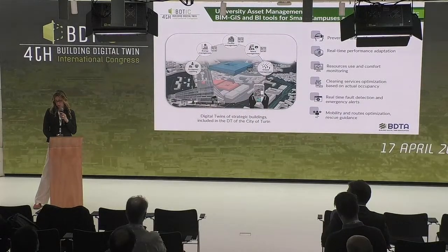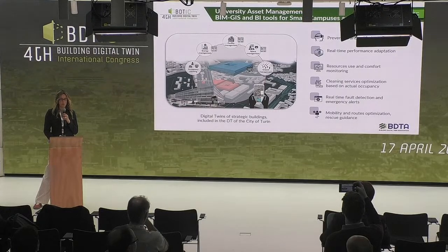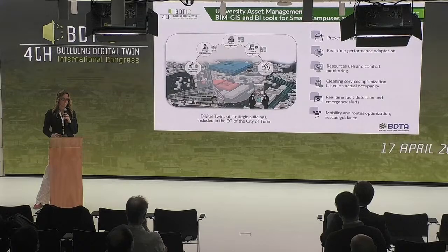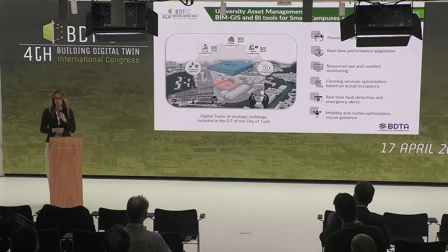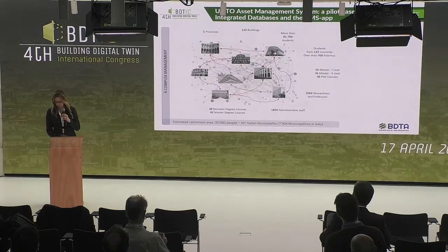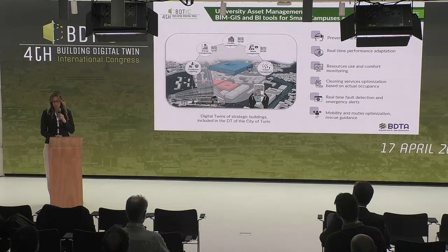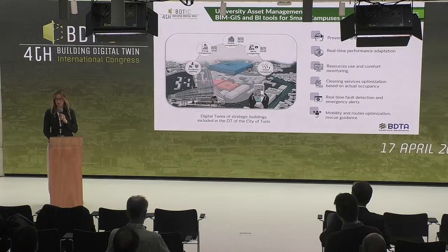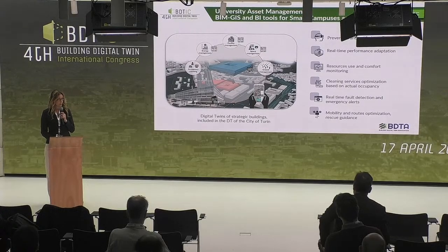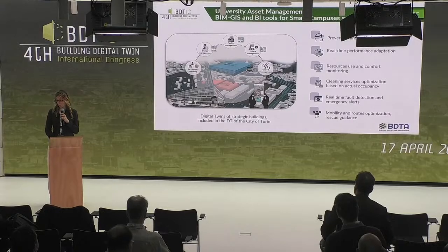So we created this digital twin. In this moment, we have some pilot buildings where we are collecting data from the classrooms about the indoor conditions, for example, temperature, humidity, CO2 concentration, VOC, and so on. And we are extending the information about the people flow, the real occupancy, because we know that if we want to optimize, for example, also the HVAC system functioning, we need to know the correct number of people inside the spaces and the lightings and so on.